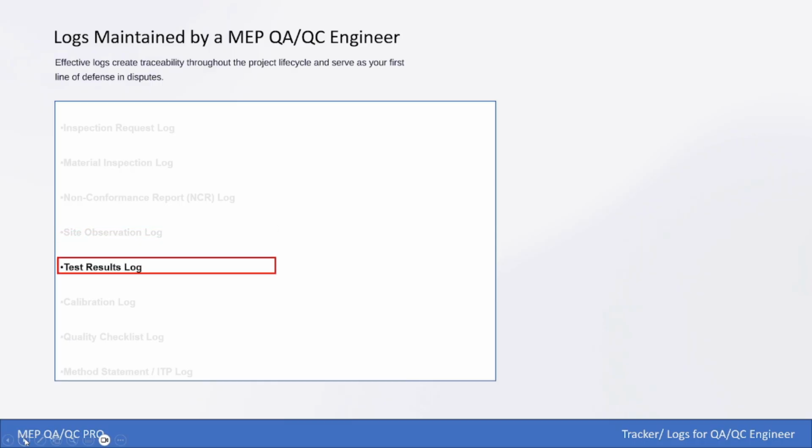The next is the test record. Test record in terms of commissioning only. Whenever you are doing material inspections for some equipment, mechanical equipment or electrical equipment like DBs, generator, UPS, and for mechanical like CRAC units, VRF units, these go through the FAT inspection, the factory test report, then the certificate log, meaning the test certificate the supplier will provide whenever you are submitting an MIR. So there will be test records that shall be shared by the supplier.